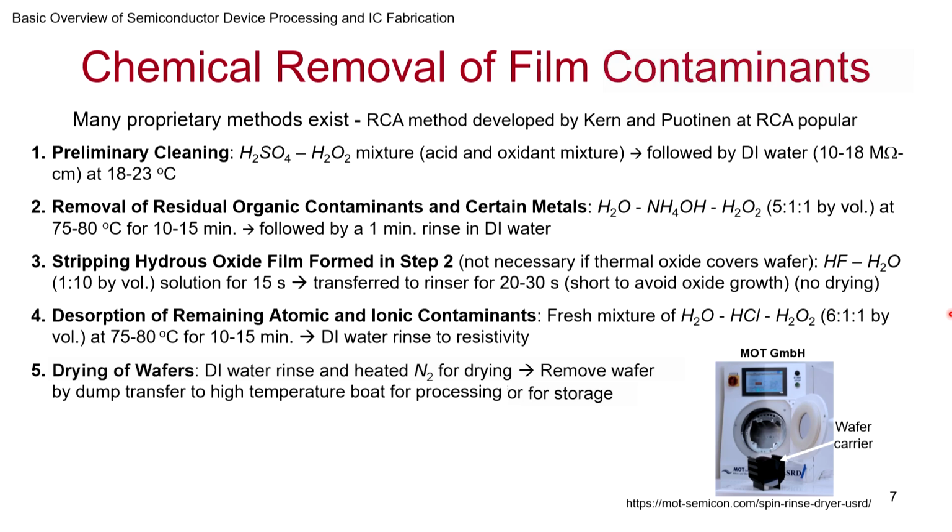But once this is done, you take it for the actual processing. You don't wait. You try your best that as soon as the cleaning is done, you immediately take it to processing, so as to avoid any other contaminant from making its way to the wafer before the next process step.